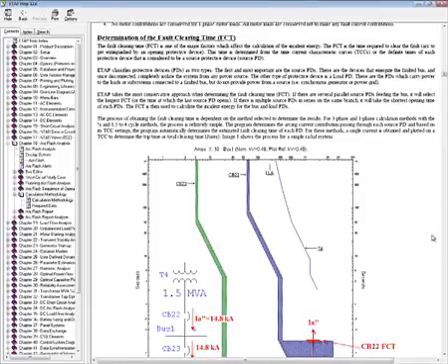As you may already know, ETAP arc flash has three methodologies for the calculation of short circuit currents in the arc flash program. Two methods are half cycle and 1.5 to 4 cycle, both of which are static currents, or snapshots in time. The third method provides an approximation of the decay in the system short circuit currents near generators or large motors. If you go to the help file, as I have here on the screen, under chapter 18, arc flash analysis and calculation methodology, you will find a detailed explanation for the determination of fault clearing times for these methods.